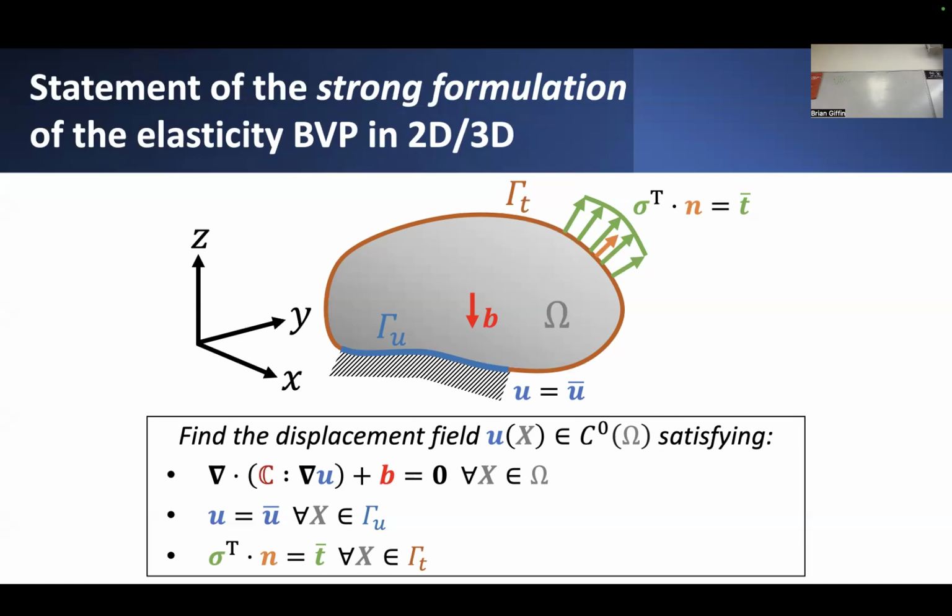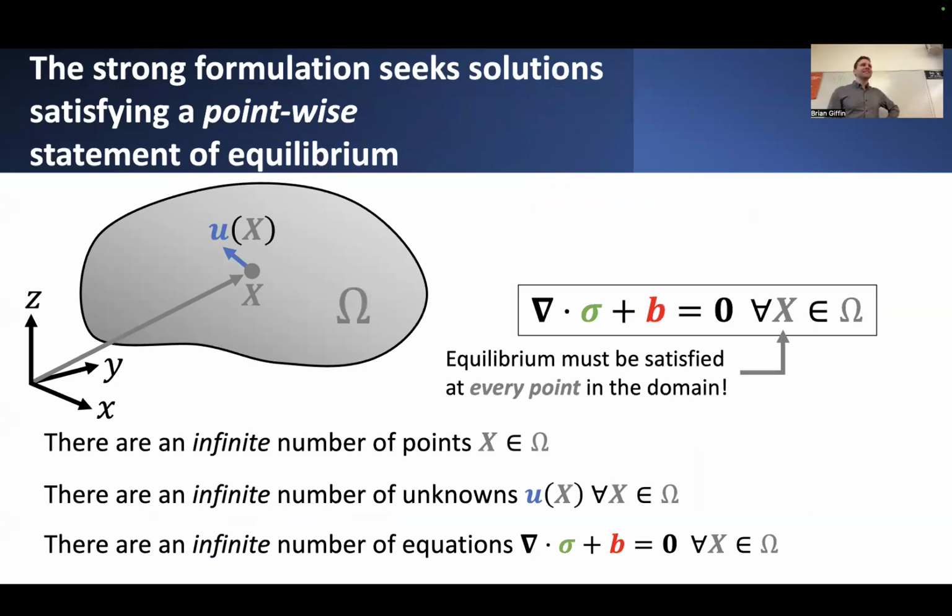So if the stress tensor itself is not expressible as a continuous function or a smooth function, then we have to contend with this issue. So we want to manipulate any terms that have some dependence on stress, or more specifically, stress divergence, into a different format so that we're not expressing them as involving some derivative of the stress tensor. Okay, so those are the issues.